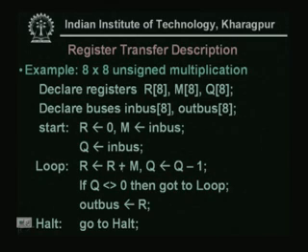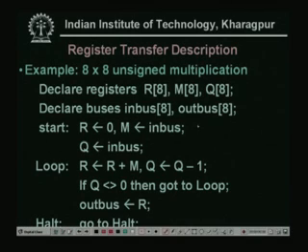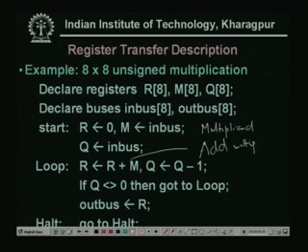So, actually this is a clear register, and the multiplicand goes to the register M. The multiplicand is transferred, and then transfer the multiplier in the next clock cycle, another operand goes to Q. Now, R plus M to R. So, add multiplicand, and the result is kept in the register R, because initially it was 0. So, as if that contains the result.